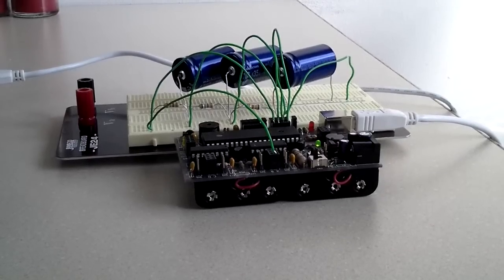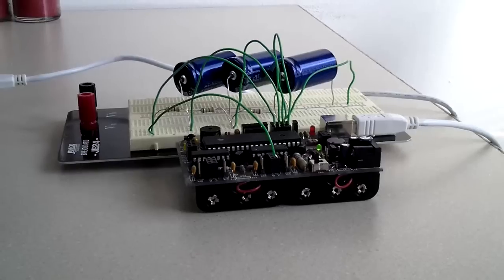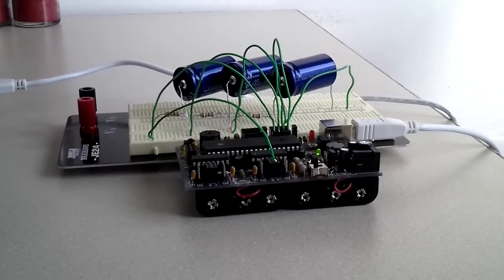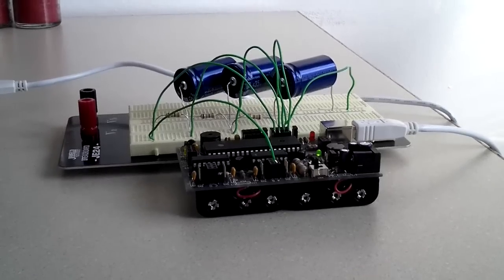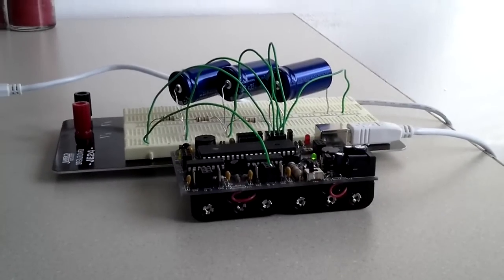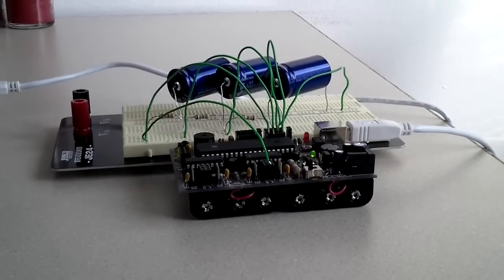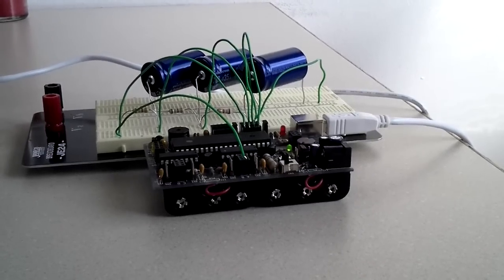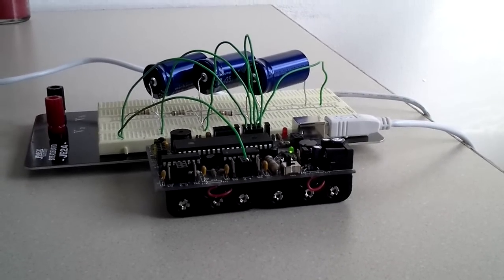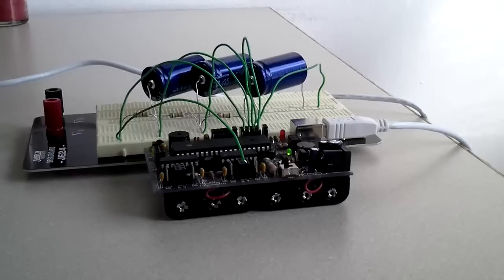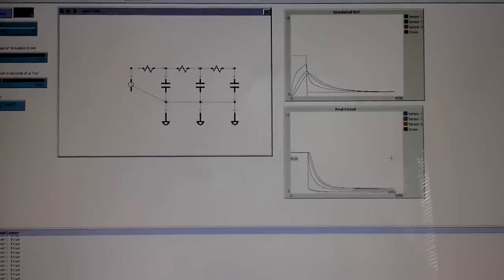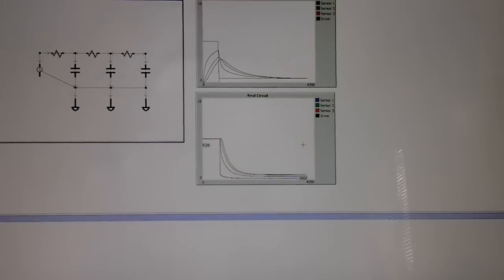This is a project I built with Samantha Brunhaver as a part of Stanford's Beyond Bits and Atoms class. The goal was to build a bifocal model. A bifocal model is when you take a real physical system, so in this case an RC circuit, capture what's going on in that real system with sensors, so in this case using the ADC, the analog to digital converters, on the microcontroller, taking the sensor data, driving that into the computer, and then comparing it to a simulated system. So in this case, we're simulating the circuit that we had breadboarded over there and comparing the two waveforms.